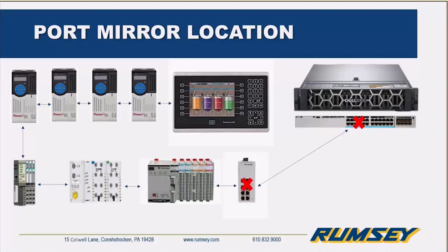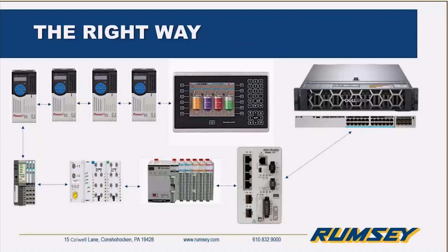So logic dictates the mirror on the ports. If you can't mirror those ports, you can mirror on the upstream switch, right? But remember, only a tiny fraction of that traffic passes through that managed switch. So the port mirror is simply never going to see data passing between the PLC, I/O, drives, and the result is basically irrelevant data. To make matters worse, it's probably a flat network on the automation side, which logically looks like a series of addresses. If there's a problem, it's virtually impossible to trace the source of the problem, even if you do have the IP address.